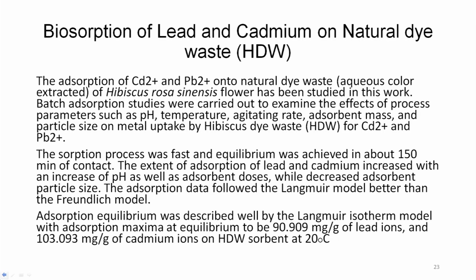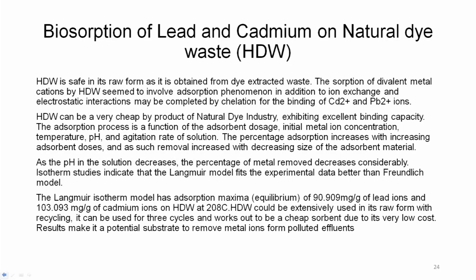Adsorption equilibrium was described well by the Langmuir isotherm model, with adsorption maxima at equilibrium of 90.90 milligram per gram of lead ions and 103.09 milligram per gram of cadmium ions onto the hibiscus rosa flower sorbent at 20 degrees. Bioabsorption of lead and cadmium using hibiscus was thus safe, as it is obtained from dye extracted waste in its raw form.